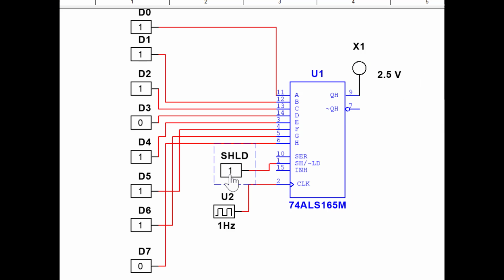So again we'll test it. Now load once again. Now 1, 1, then 0, then 1, again 1, again 1, then 0. So if you clearly see, your parallel data is getting transferred to the serial fashion. This is all about your parallel in, serial out shift register.